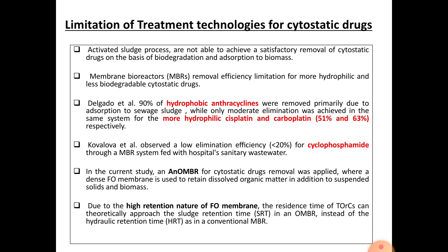So there is a limitation because the MBR cannot remove hydrophilic substances well, and less biodegradable cytostatic drugs were not removed with 100% efficiency through membrane bioreactors. So there were some limitations of these membrane bioreactors.